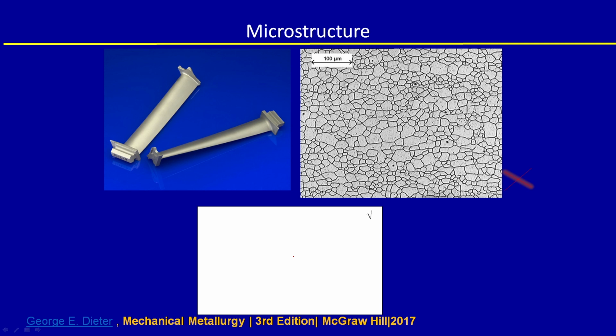So, if you want to have low creep at high temperature, you need to have single crystals, because creep is governed by grain boundary sliding. So, it is better to have some kind of a single crystal without many grain boundaries, then it is possible to reduce the creep.